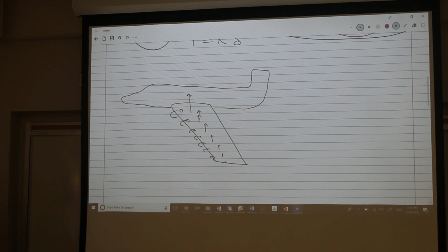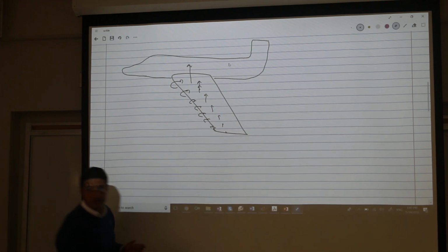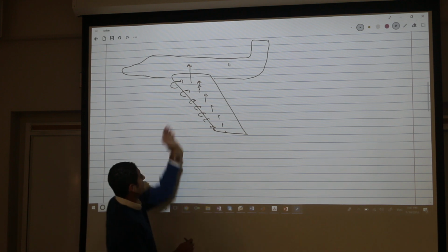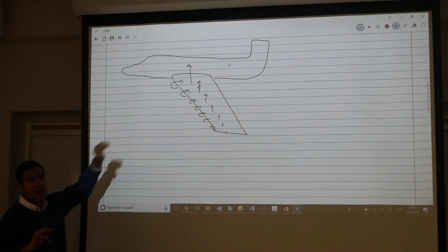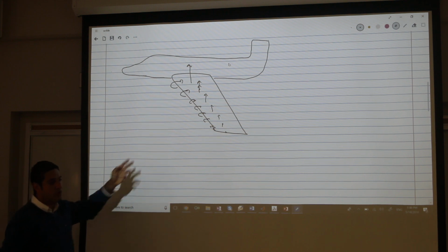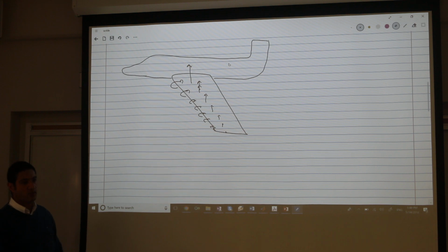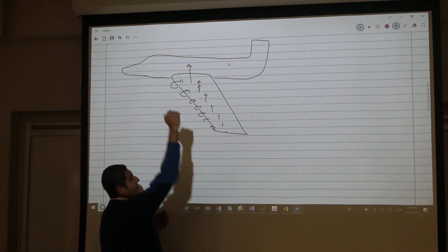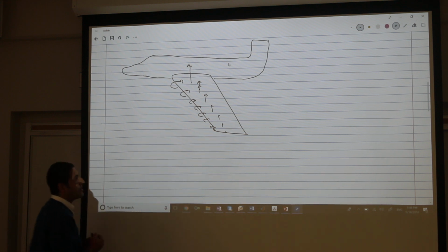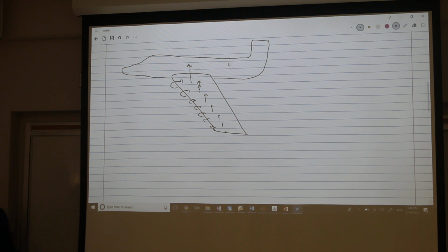You might have the same distribution. So again, this is a cantilever beam, right? And if you have this kind of moment, which is from an aerodynamic point of view a pitching moment, now from a structural point of view, it's called what? Twisting moment, exactly. So this lift distribution bends the beam or the wing, and this moment distribution twists the beam or the wing.